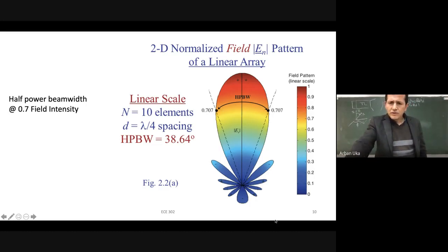So we'll often worry about this distribution. We're going to talk about this distribution of the antenna in detail, but from here you can see that there is a major lobe, a major direction which has a high intensity, and we have some smaller lobes, or some smaller distribution of the energy in some other direction, with a narrower angular selectivity, okay?